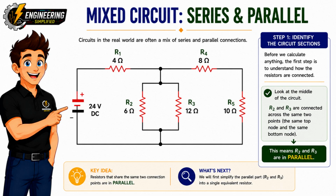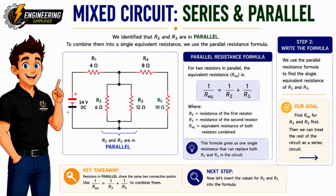Before we start calculating, the most important step is to understand how the circuit is connected. If you can identify which resistors are in series and which are in parallel, the calculations become much easier. Let's start by looking at the middle of the circuit. Notice that R2 and R3 are connected between exactly the same 2 junctions.